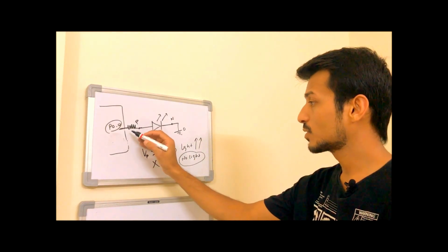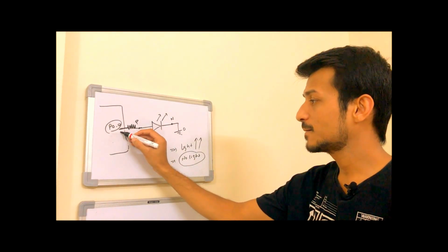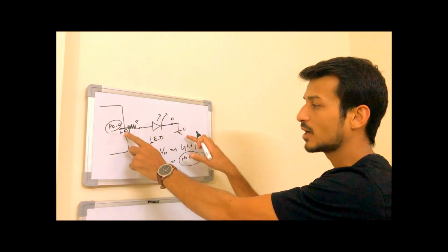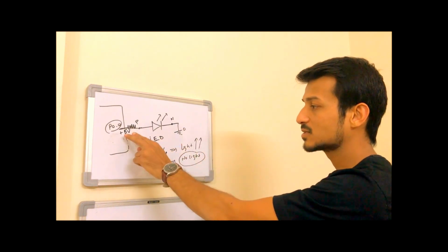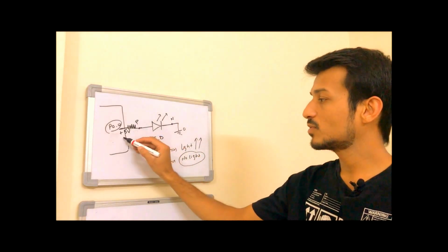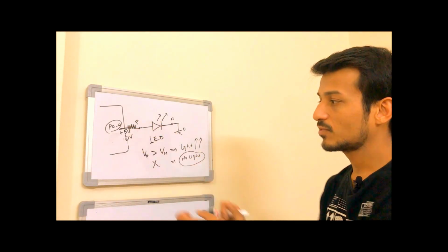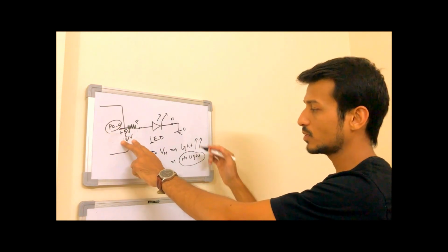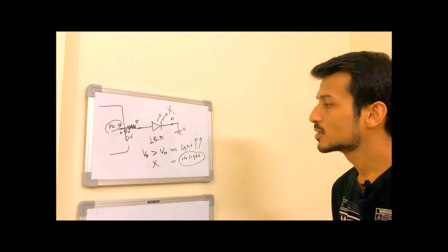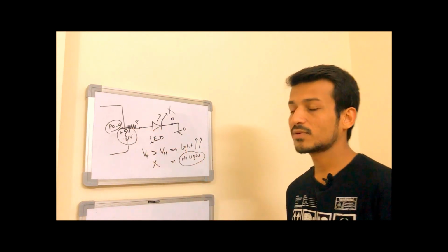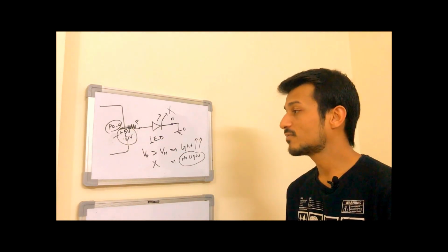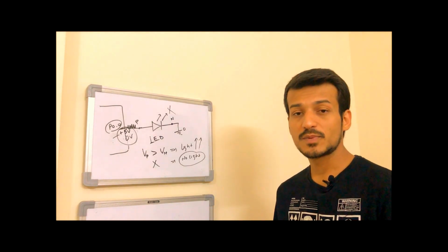And if you set this pin as high, meaning plus 5 volts, there is a difference between this PN junction layer and the diode is forward biased. The P part is 5 volts and the N part is 0 volt. It will emit the light. But if you clear this GPIO pin, which will have 0 volts, and 0 volt matches with 0 volts, there is no light in this condition. So we are doing this in our software. We are taking care of making this pin high and low repetitively at the rate of 500 milliseconds. Let's see it practically.